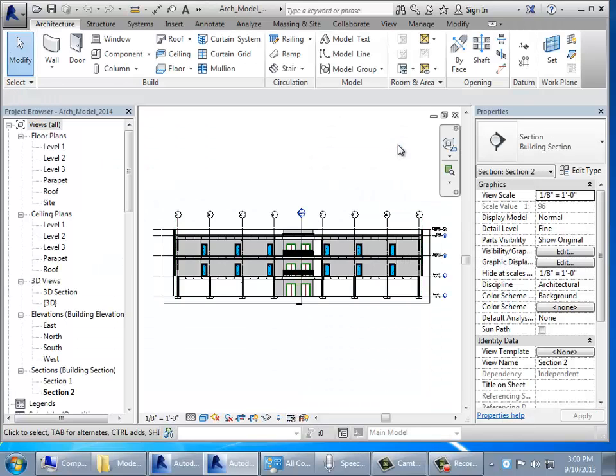Now in this case, the architectural model is not going to complain right offhand because it actually still found the thing that had the old name. I didn't actually delete that and wipe it out. But if I really want to link it to the new structural model as opposed to the old structural model, what I should do is do a reload, kind of pull that in there together.